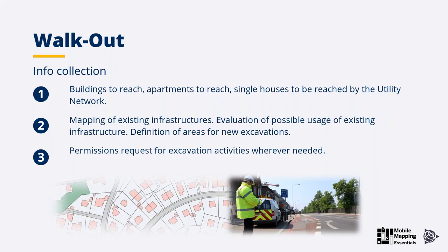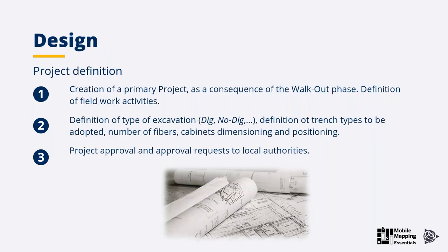According to this scouting or walkout investigation, it is then possible to estimate which permissions might be requested in order to start digging a new trench, and maybe connecting by making use of some specific poles or things like that. This kind of investigation a priori is what is called the walkout, which in general consists of quite a detailed mapping activity.